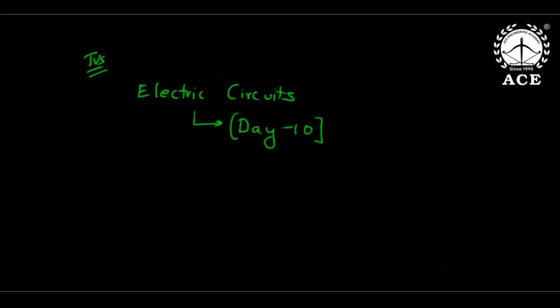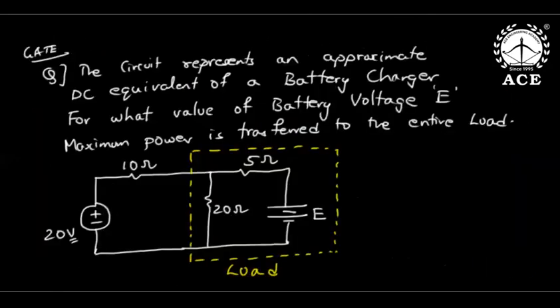So what I will do here, everybody observe. Because we cannot reduce and directly argue load resistance equals source resistance, but one thing we know under the Pmax transfer theorem, 50% of the supply will drop across the load. So if this load is really absorbing maximum power, then these terminals are the load terminals. How much drop will occur? 50% of the source. The source is 20, so this is 10 volts, 50% of Vs. That is the logic. Now that this voltage is 10, I'll write KCL.